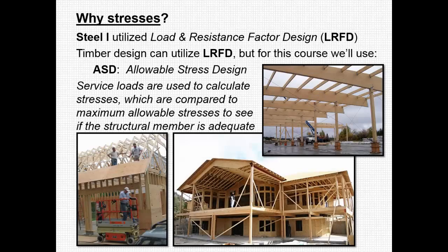One thing we want to question is why stresses. In Steel 1, we used the LRFD, which was the load and resistance factor design. In timbers, we can use that, but of course we're going to use the ASD, which is the allowable stress design. Service loads are used to calculate stresses, which are compared to maximum allowable stresses to see if that particular structural member is adequate.